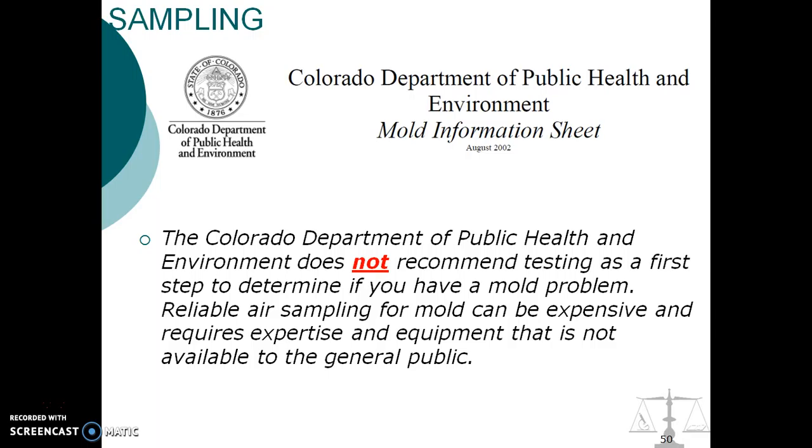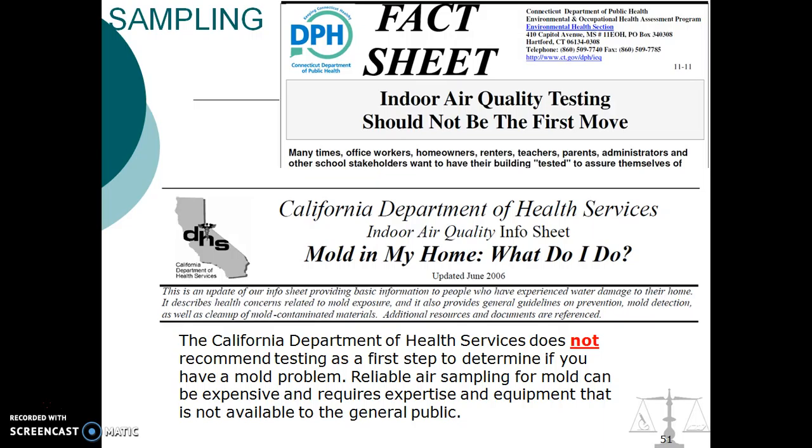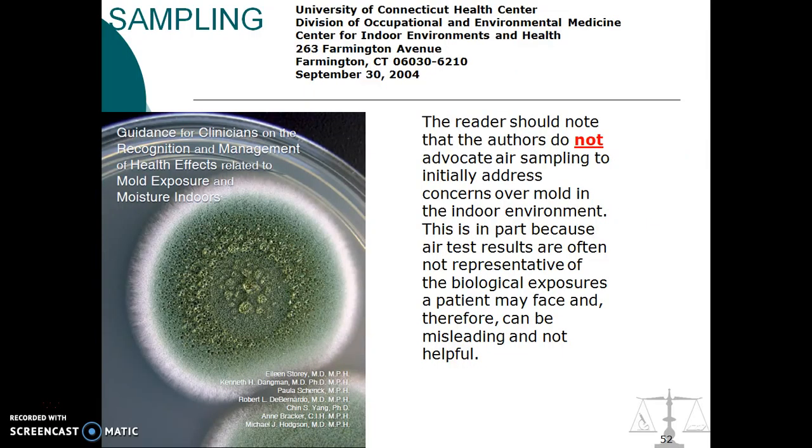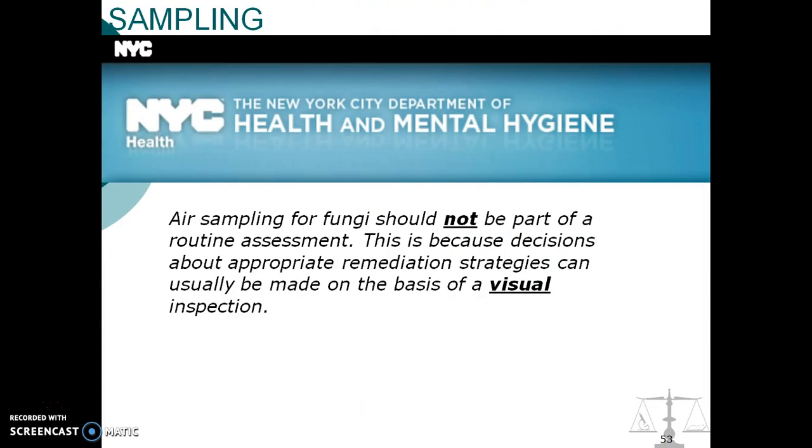The state of New Jersey, the state of New York, the state of Pennsylvania, Nevada, all of these states say do not collect samples. The samples are meaningless. Do not waste your time. Connecticut, California, Nevada, all these states say don't be collecting samples. University of Connecticut Health Sciences Center Division of Occupational Environmental Medicine says do not collect air samples. They're meaningless. New York City Department of Health and Mental Hygiene states air sampling for fungi should not be a part of routine assessment. This is because decisions about appropriate remediation strategies can usually be made on the basis of a visual inspection.